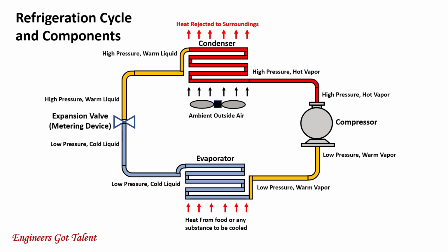Going back to the expansion valve, inside the valve is a diaphragm which is connected by capillary tubing to a thermostatic capsule at the exit of the evaporator. The change in pressure at the capsule travels along the capillary tube, and the change in pressure moves the diaphragm up and down. The up and down movement of the diaphragm allows less or more refrigerant to pass through.